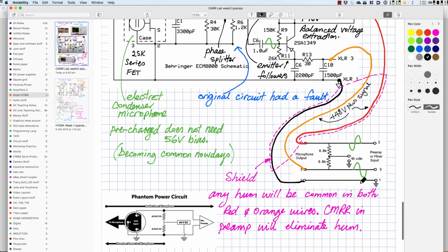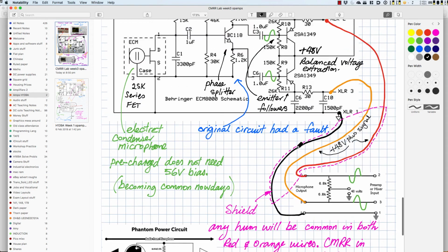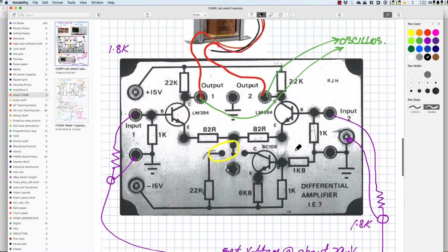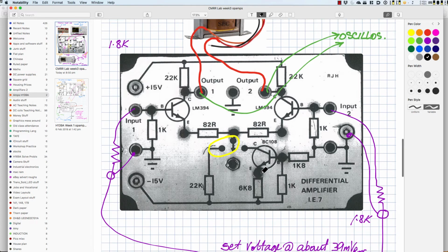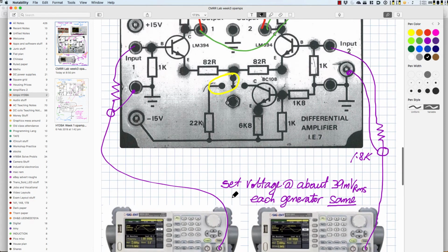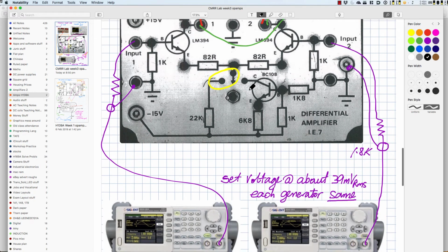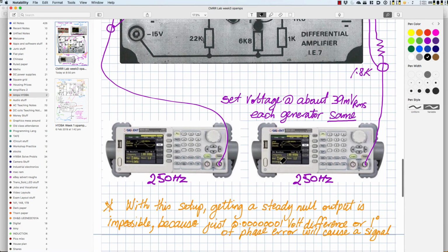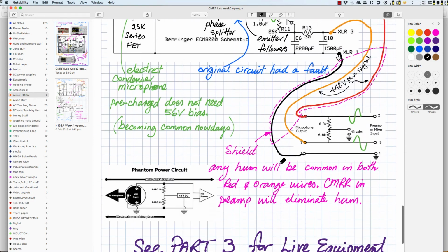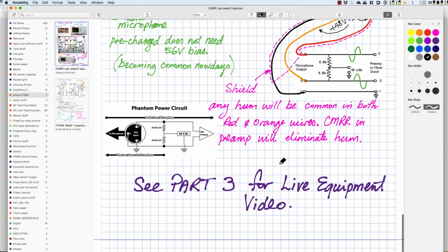And that's what we've been talking about, because this preamplifier here is always going to be starting off, whether it's an operational amplifier or whether it's done with discrete components, as a differential pair. And the beauty is that we then can have our differential amplification factor and our common mode, very low hopefully, amplification factor, and therefore we eliminate the hum and we only amplify the good part.